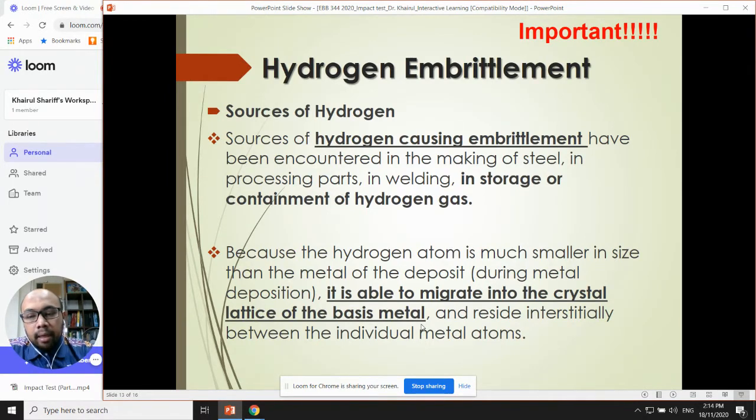So that means the hydrogen from the hydrochloric acid, HCl, attacks the surface, maybe through the vapor of the acid. That's why, when you install something related to metal, please make sure acidic conditions are excluded from the environment.